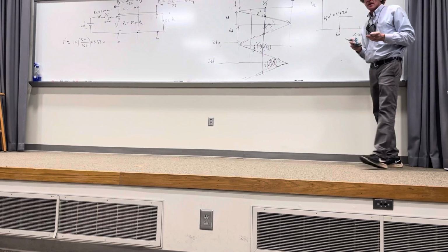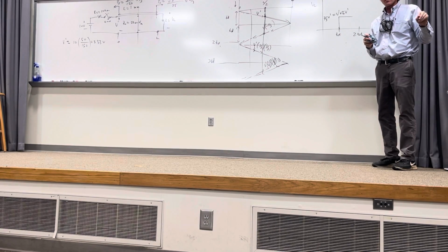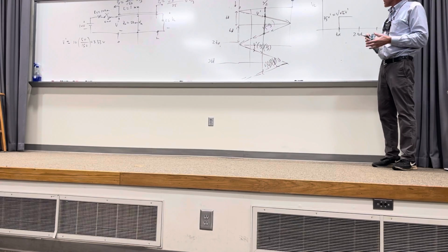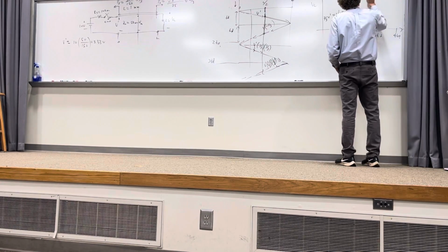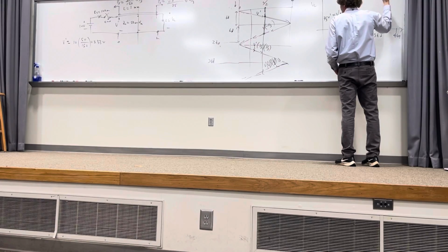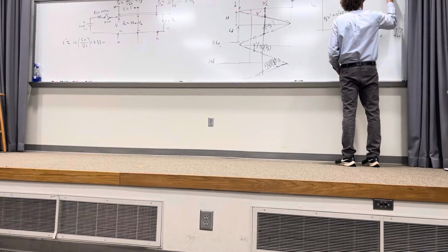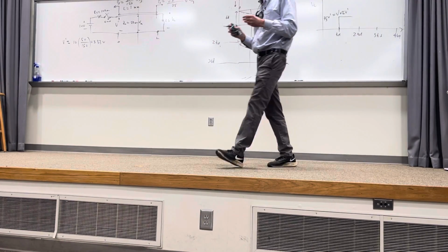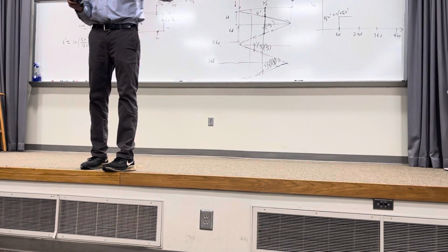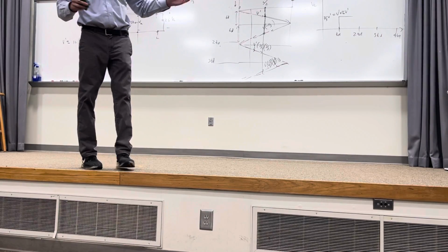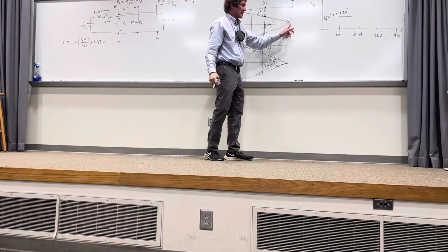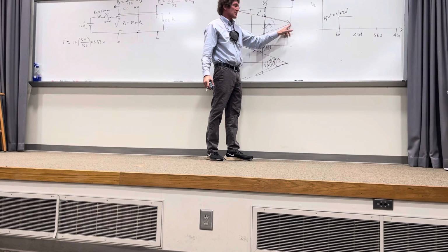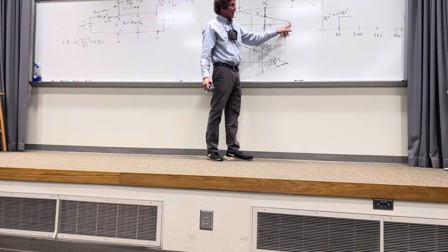And now I'm going to make a comment that you're going to hear over and over again in EMAG 1 and 2. If you have 1 plus the reflection coefficient at the load or source, that is called the transmission coefficient at the load, tau sub t. Because that's how much of the wave is actually transmitted to the load, the voltage. With me? Remember, as soon as this thing hits, instantly there's a reflected wave. So you have to add the reflected to the incident wave at that point. Y'all with me on that, class? That means that's going to be different.